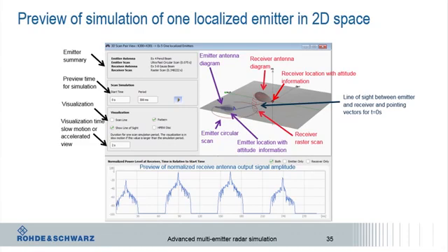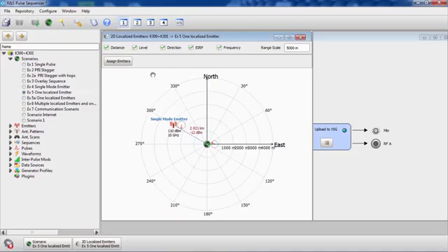In this case, you see 4 antenna turns, the first one having a lower level, the middle one having a higher level, and the last one again having a lower level. This is coming from the raster scan of the receiver, which is scanning the emitter antenna under different angles of its antenna diagram, and therefore leading to different power levels. So now let's really have a look in the simulation software.